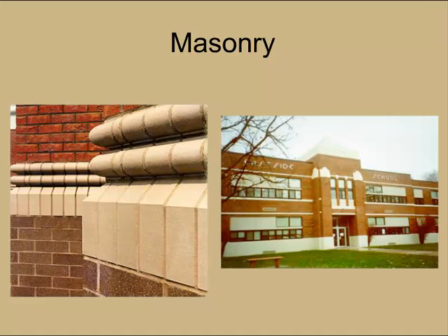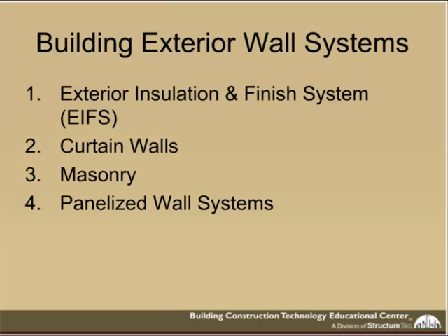Next, on the right-hand side, I spoke about the concrete construction. We have a split-face concrete block here, very, very common in commercial construction. If you've seen a lot of retail stores, they would have this. One of the major downfalls here is it's very, very moisture absorbent. So you need to make sure it's coated. And you can see that on the left-hand side of the photo. You can see that it's coated, and it actually has that wetting action. You need to coat it to support with that moisture resistance. But it's very, very important, and Russ is going to talk about this in a little bit, to make sure that you don't suffocate the wall system with improper coatings. So good executive summary of masonry wall systems.